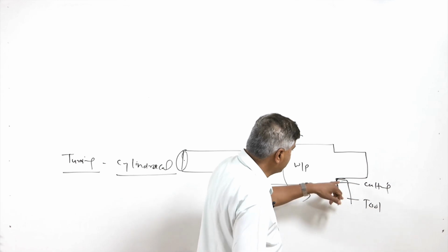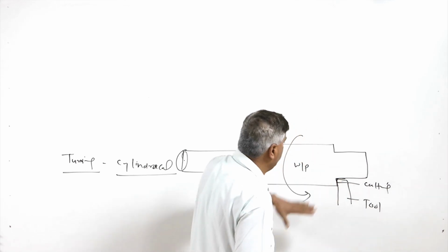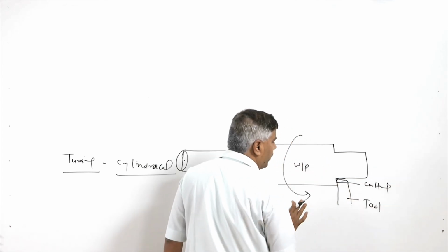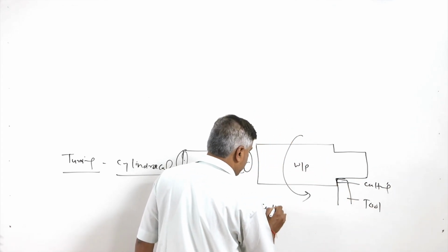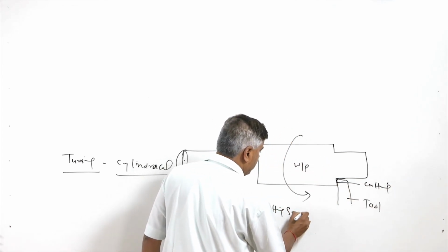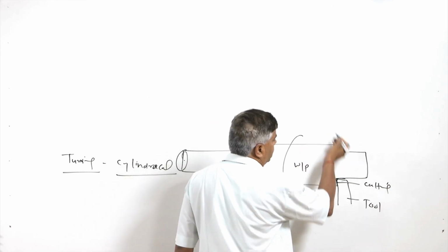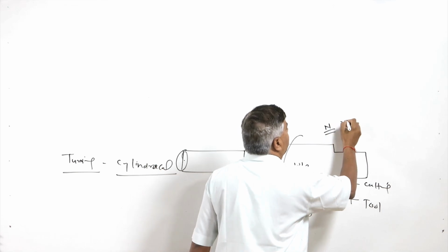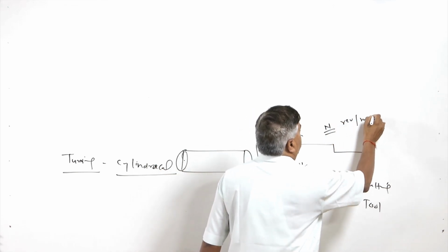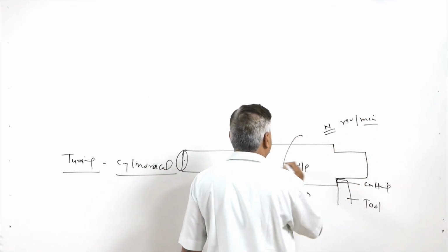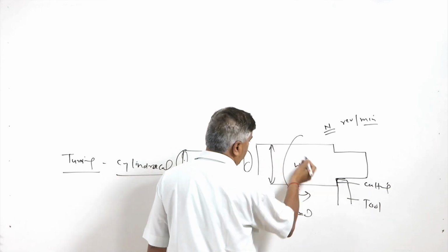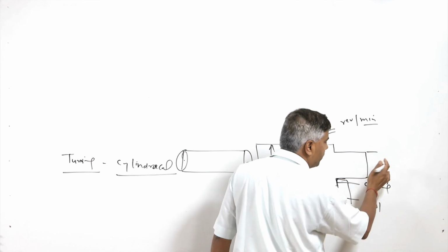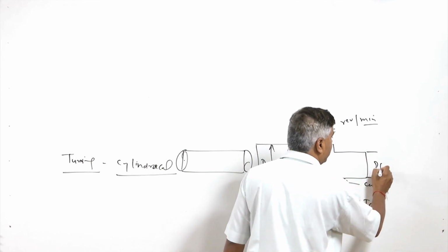In this case, since the cutting edge is fixed and the workpiece is moving, the relative movement between the cutting edge and the workpiece is called cutting speed. Say the workpiece is rotating at n revolutions per minute, the diameter of the workpiece is Do, and the final diameter of the cylinder produced after one cut is Df.